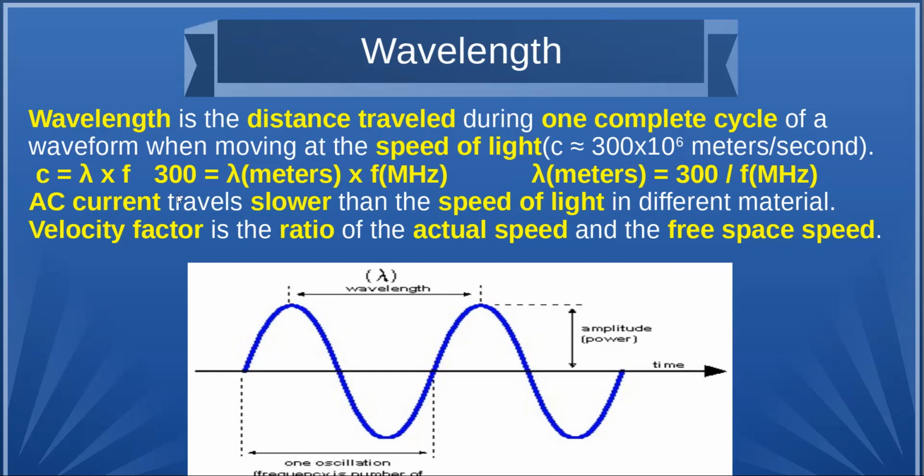Or it's built in. There's another formula, which I didn't put on here. Use 468 divided by the frequency. And the answer comes out in inches because they've already factored the conversion factor in there, and it gives you inches for half a wavelength, which is another one that's commonly used.